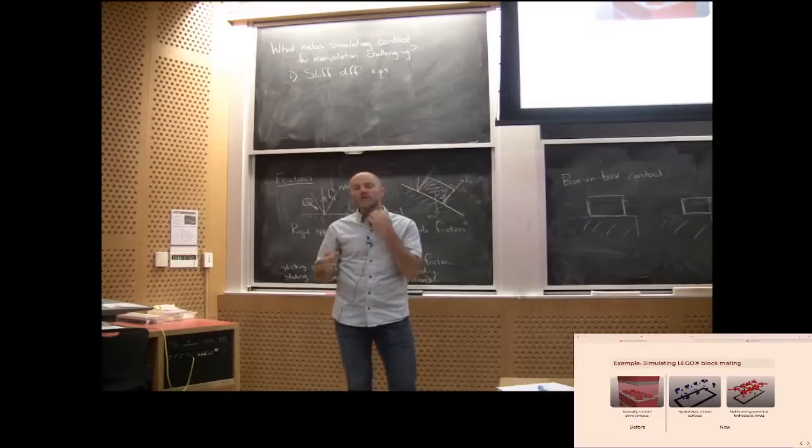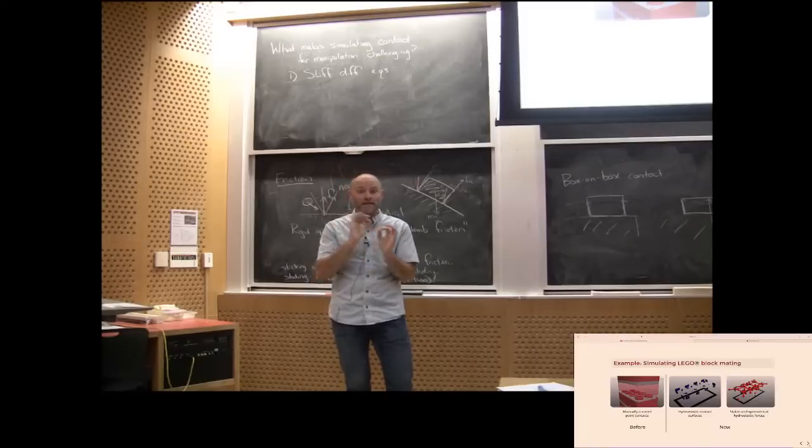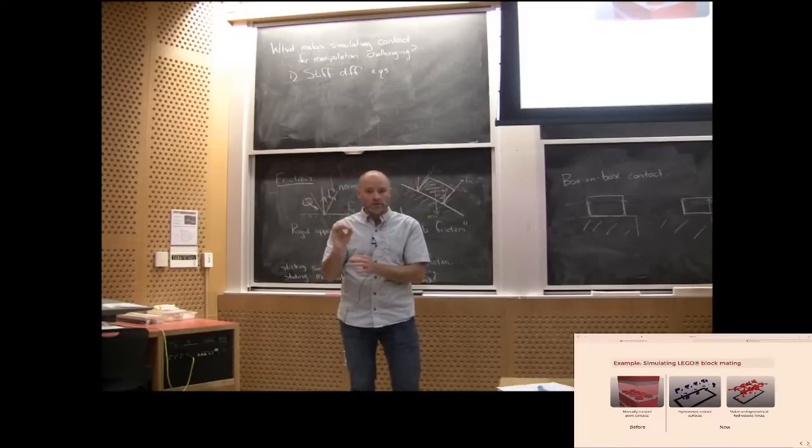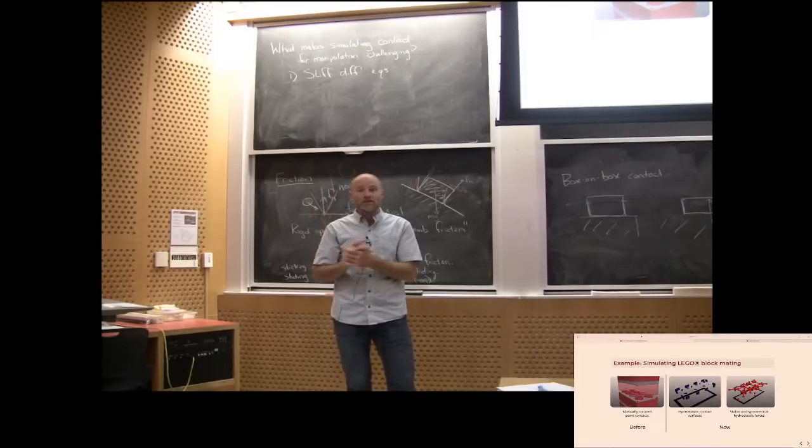It depends on which simulation, and it depends on the mesh tessellation. You have to take your surface mesh and make it a tet mesh, and the number of finite elements in your tet mesh will be the computational cost. So the reason it is not on by default in Drake is because it's slower, but it's actionable. We choose to turn it on often in our manipulation workflows.